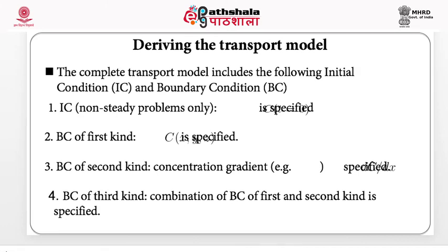Now that we have a model, just as we had in the flow problem, we also have to define the initial conditions and the boundary conditions to complete the transport model. As we said, in a flow model, an initial condition deals with a non-steady or transient problem, and in this case, concentration instead of head, at time equals 0, or at the start of the simulation, has to be specified. When we are dealing with the steady state problem, instead of initial condition, we need to define boundary conditions.